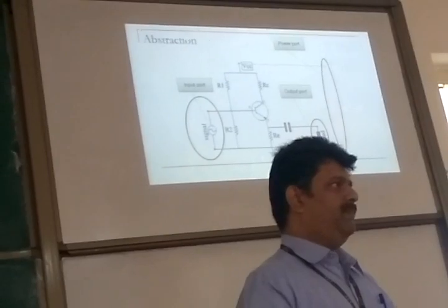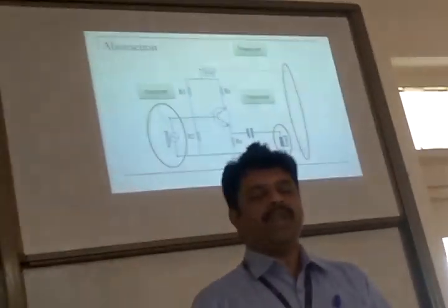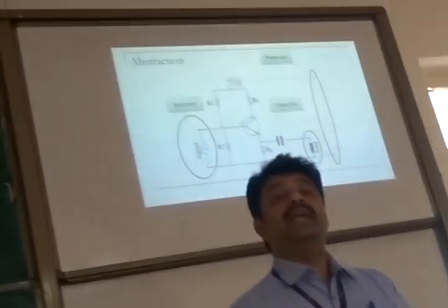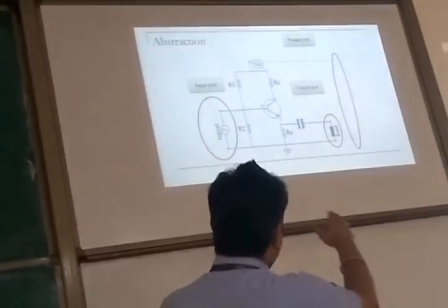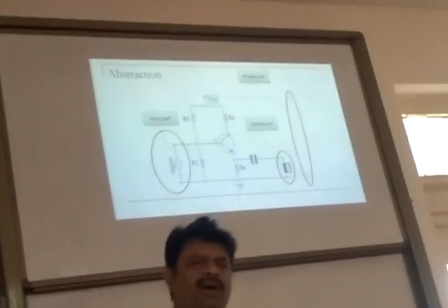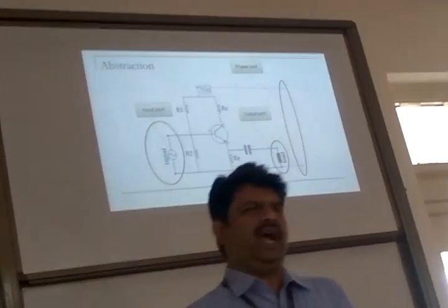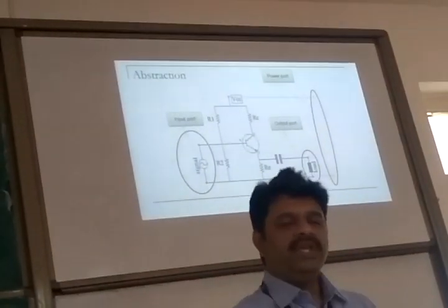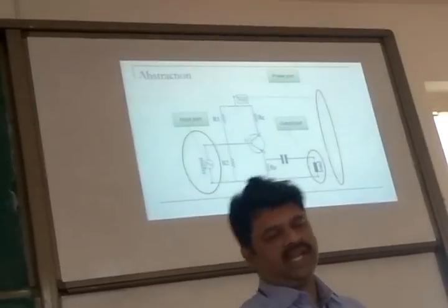You can choose your R1 value 1K, 2K, like that, or you can put a variable resistor and tune according to your requirement. Except for that, all the transistors, the rest of the resistors, capacitors, all these components are the same. I don't want to change them at all. Gain can be adjusted with only one resistor. So give provision for the people to connect the resistor.